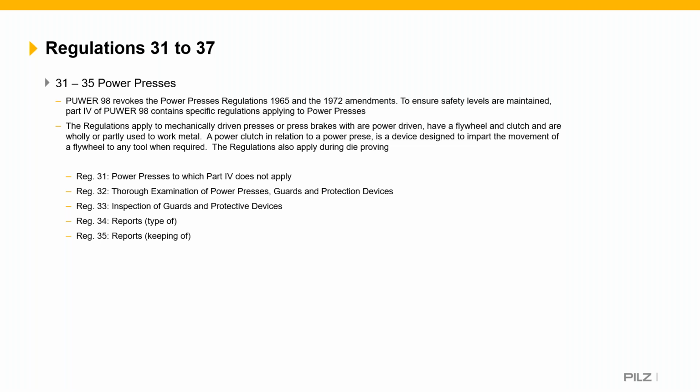We'd also need to ensure that a power press is not used after the expiration of the 4th hour of a working period, unless every guard and protection device has been inspected and tested whilst in position on the press by a person appointed in writing, or there are automatic checks and things that can be done within that. So again, we're looking at persons who are competent, with certifications and proof of competence and so on, so that they can go on and conduct the tests as required and as stated within there if these tests aren't done on an automatic basis.